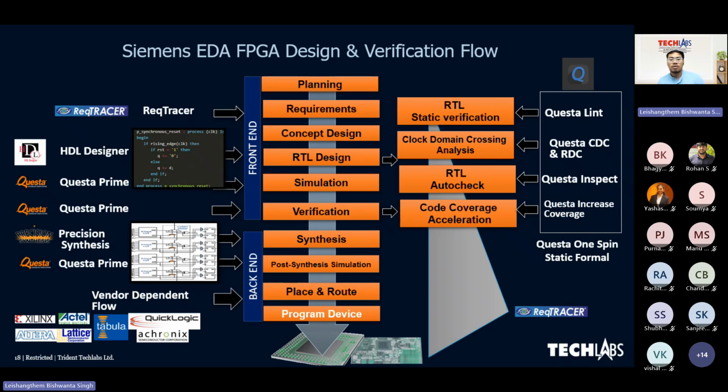And when we go for level A and B, DO-254 also mandates performing formal analysis for your design. One among many formal methods of analyzing your RTL is RTL auto check. For that, Siemens EDA has Questa Inspect, which can perform formal verification of your RTL.